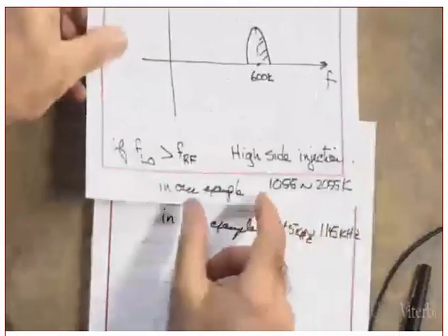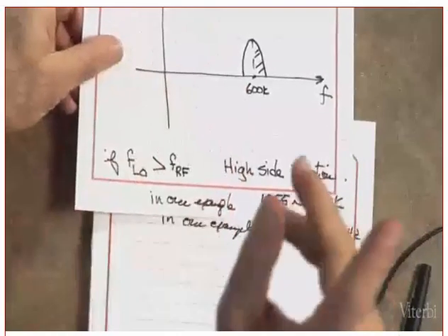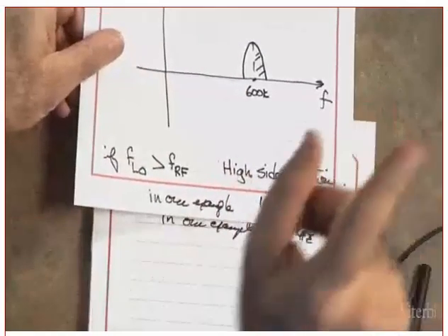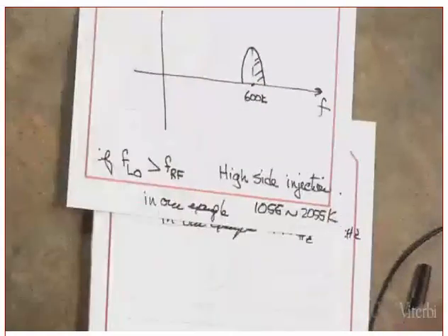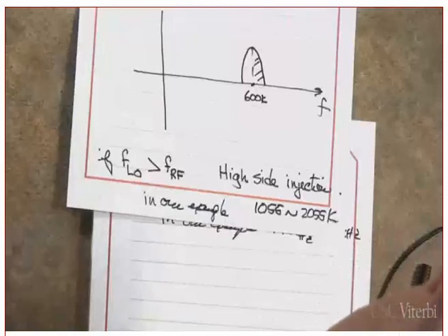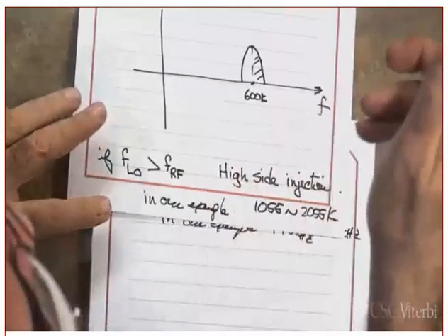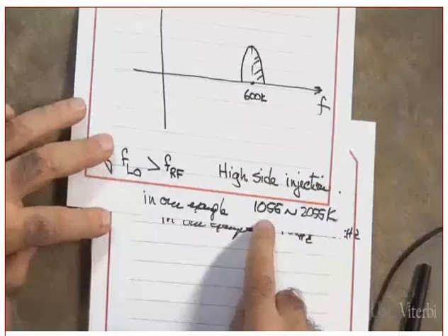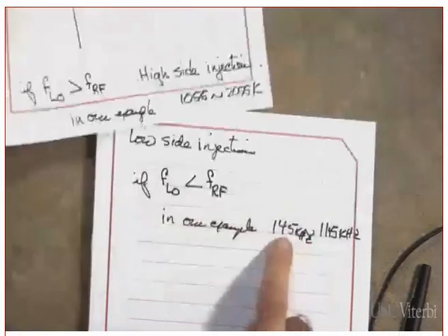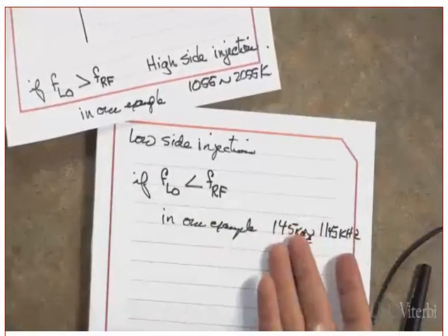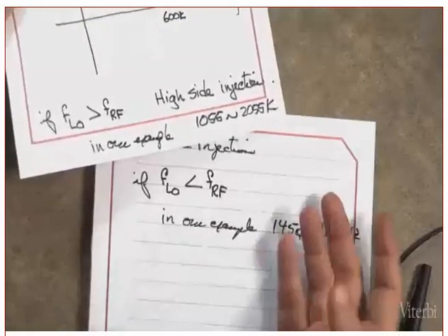Let's look first of all at the tunable range of your VCO. If you divide the high frequency over the low frequency, if the number is small, it's easier to design the VCO. Did you understand what I just said or not? This is the range of the synthesizer. Divide this by this. What do you get? Approximately 2. Divide this by this. How much do you get? Roughly 8. You follow me or not? This one is easier to design than this one. Did you get my point?